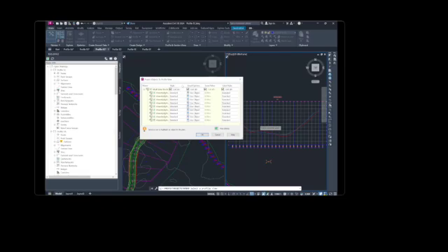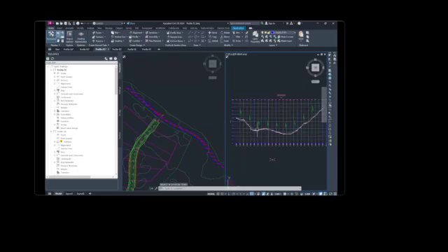In the Project Objects to Profile View dialog box, we can set all, there we go. The parameters are style, projection without exaggeration, elevation option, surface first, street surface, label style, object name, station and elevation. Click OK. Now the light poles are displayed on the profile view.